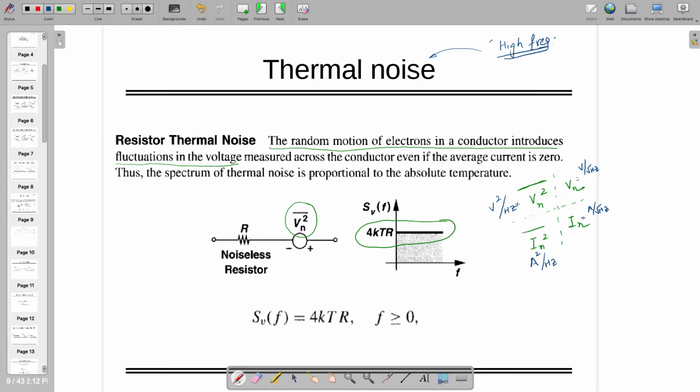If you are taking the integrated noise, it is measured in terms of either voltage or ampere. There is no hertz because it's integrated from some frequency to another frequency, so it's not with respect to some hertz, right? So it's a band of frequency.